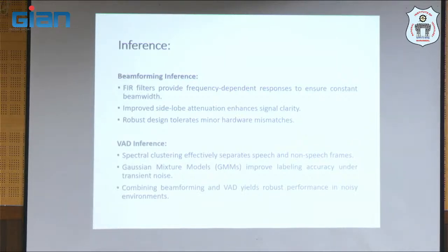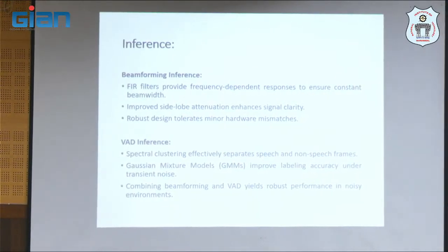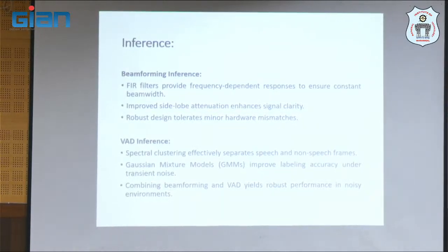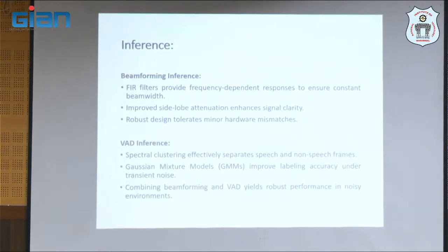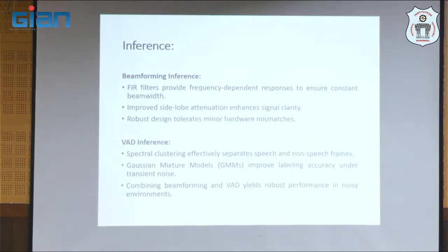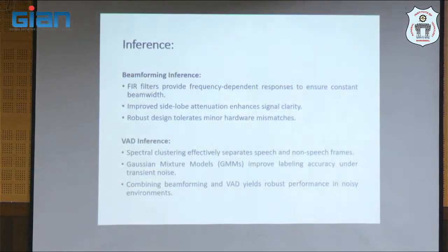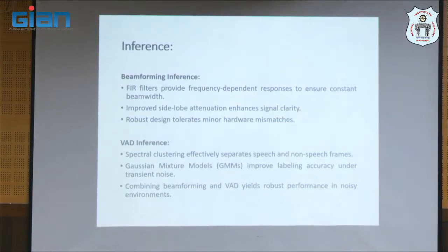In a single microphone case, we use a single weight, but for wideband signals that is not acceptable, so that's why we use FIR filters. We give different weight coefficients for different frequencies to get constant beamwidth. We can achieve this by the temporal filtering technique, by creating multiple signals with some delay between them to ensure constant beamwidth.